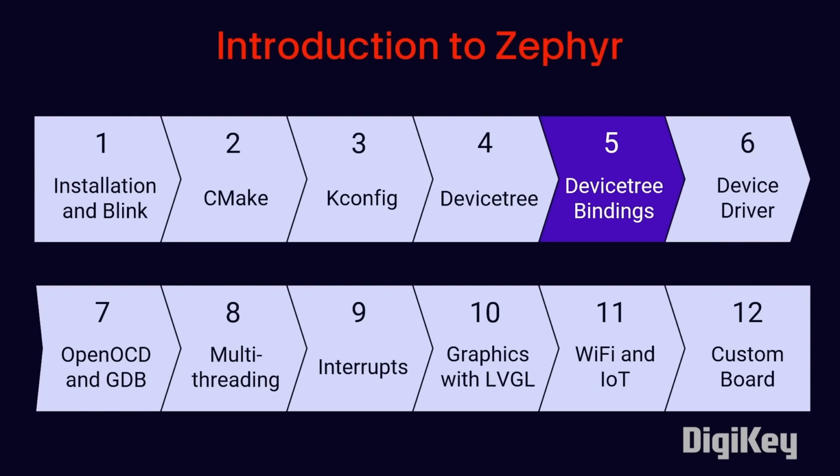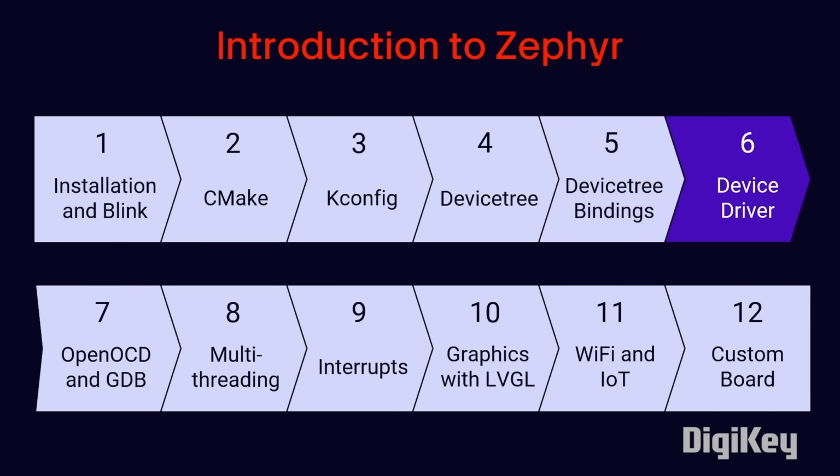We'll introduce yet another markup language, YAML, that Zephyr uses to describe the interface between the device tree and driver code. We'll look through Zephyr's analog to digital bindings and code to understand how a device driver is constructed. We use this information to create a simple analog to digital demo. We culminate this section on the device tree by writing our own device driver. It's a very simple button wrapper, but you get to see how Kconfig, Devicetree, bindings files, and C code all work together. You'll also be challenged to write your own simple I2C driver for a temperature sensor.